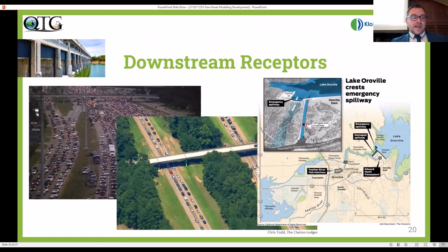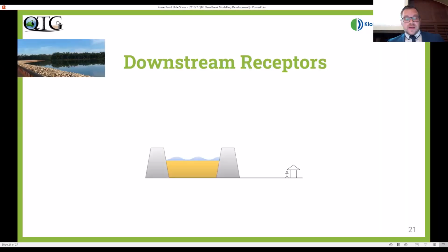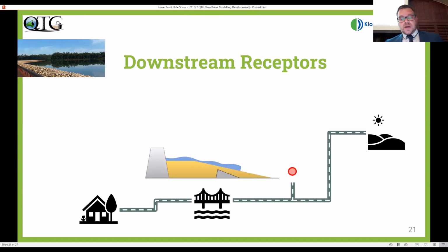And later, the Oroville Dam incident provided a great data set to evaluate the effectiveness of mass evacuation of urban areas. A life simulation model is a dynamic network model. What that means is for each population location, it's represented individually as a node or a point. Roads or paths create a vector network, and our breach model or flood model or bushfire or lava flow, anything that moves over space over time, can be represented.